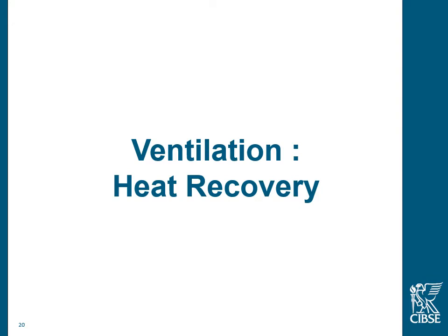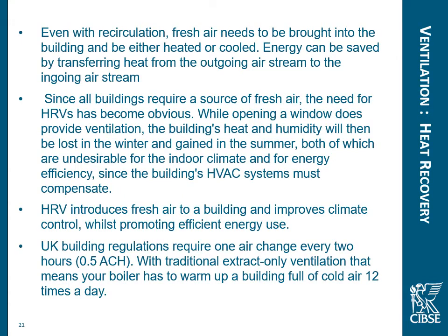Now, where we do have ventilation, it's essential that we use heat recovery. Even with recirculation, fresh air needs to be brought into the building and either be heated or cooled. Energy can be saved from transferring heat from the outgoing airstream to the incoming airstream. Since all buildings require a source of fresh air, we could bring in fresh air from windows, but when we do that, we let out all the heat. We could just use mechanical ventilation and extract, but again, we waste all the heat.